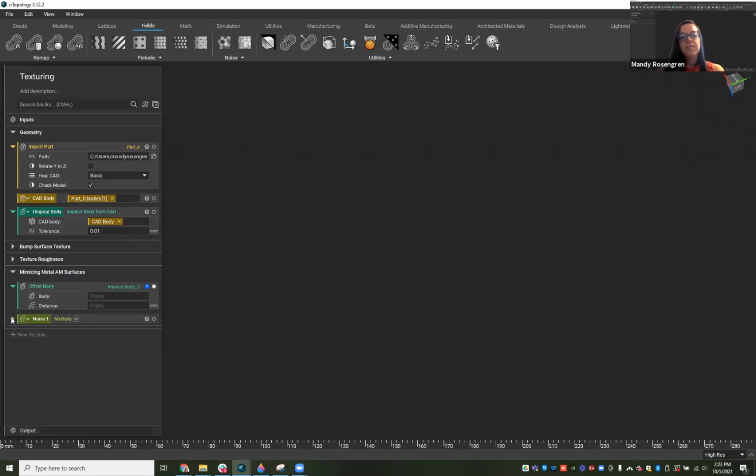So I have one simplex noise 3D, one type of roughness, and maybe I want to combine it with another one, get that combination. So I'll again follow that same step, where I can multiply it. I'll have my simplex noise 3D as one option. This time I want my frequency to be 500. And I'm going to multiply by 0.2 millimeters.